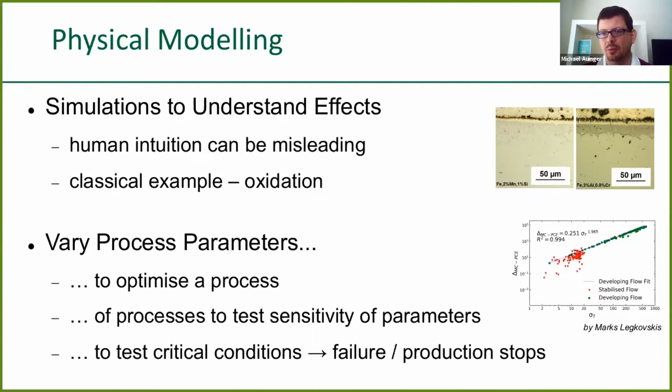What the general approach of literature was saying was that grain boundary oxidation must be enhanced in those systems. If you compare this to simulations, you will see that the grain boundary oxidation follows exact predictions as one would expect, but instead it's the internal oxidation in the grains, the denser gray shaded area, that's actually hampered. So in other words, people were barking up the wrong tree for a couple of years by following human intuition and looking at the image and getting the impression that grain boundary oxidation must be enhanced, whereas it's actually the internal oxidation that's slowed down. Now, this is not the solution of the process, but it's a very important piece of the puzzle in order to find a solution.